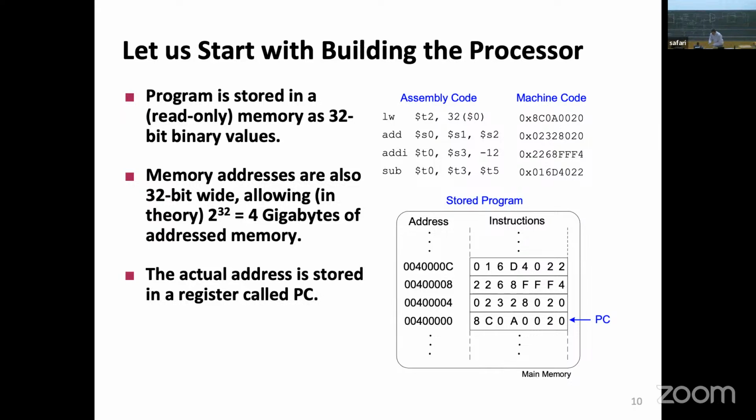Okay, let me just add the correct numbers there, 0 and 1. 0 is ALU, 1 is reading from the memory. And obviously, once I have something from that, it will be another control. So this is Mem-to-Reg. And I have yet another control signal that goes into the cloud, Mem-to-Reg. For the R-type, Mem-to-Reg is 0. And for the load word, Mem-to-Reg is 1. Now, before we go to the break, just a quick summary. We will be writing back to the register, so the write enable will be 1.